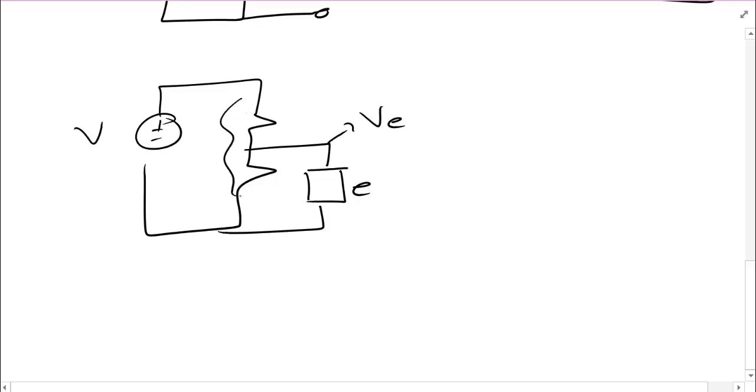I won't need to reanalyze the entire circuit. Notice one important thing though. If this is a resistor, then I need to compute R2 as the parallel connection of my two resistors. This is one of the reasons I said it's not a particularly good voltage source, because depending on how you load it, the voltage will change. But as long as you know how you're loading it, you can compute the voltage knowing the voltage division principle.